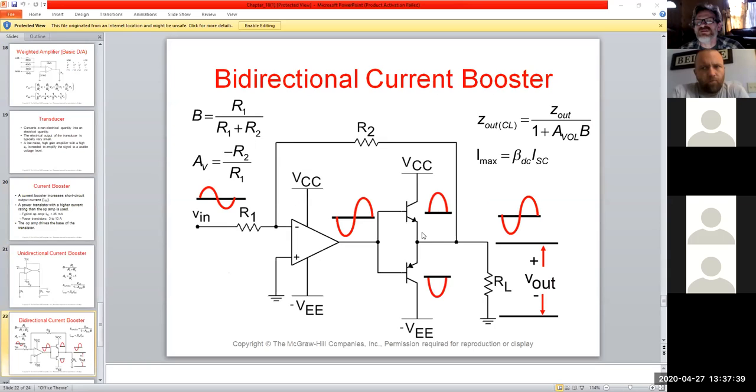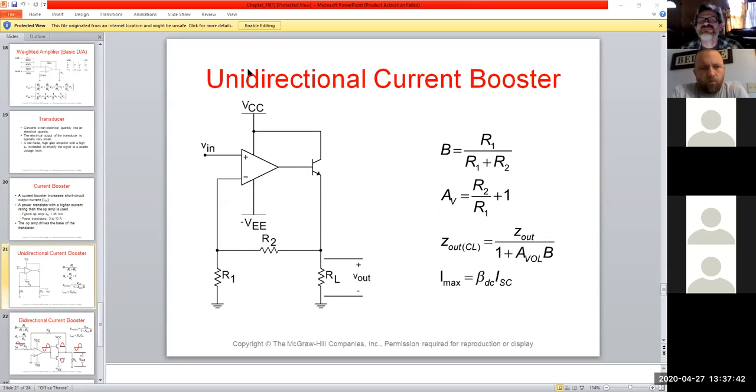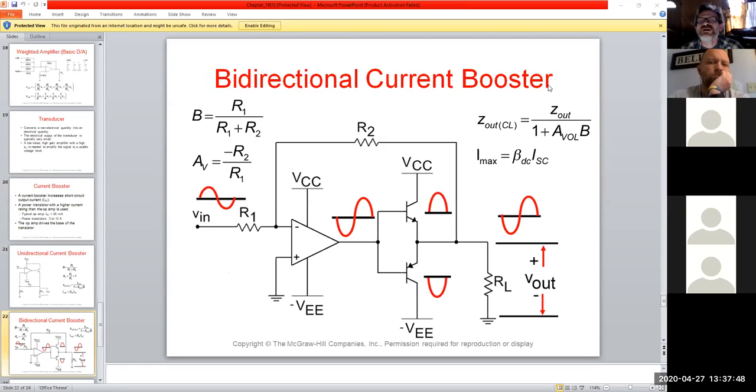And then on the same principle, but instead of unidirectional, with just the one NPN transistor there, now we go with a bidirectional, where you would get an NPN and a PNP. That way you would get both alternations without the clipping. So you clip on a positive, and then on the negative, and our reproduction would be the full output signal here. That would be if we're looking for, instead of a rectified signal, a full boosted signal on the output.